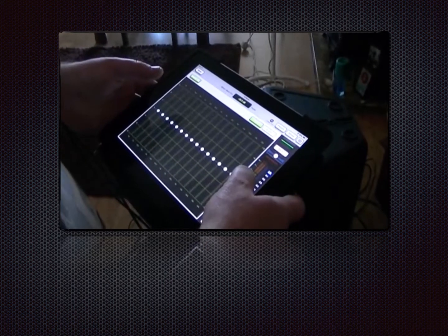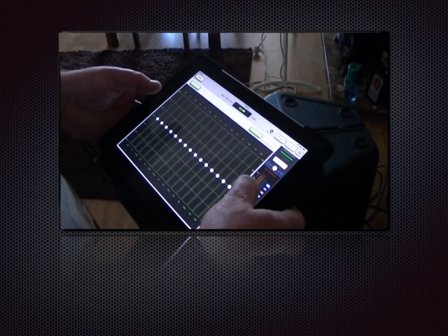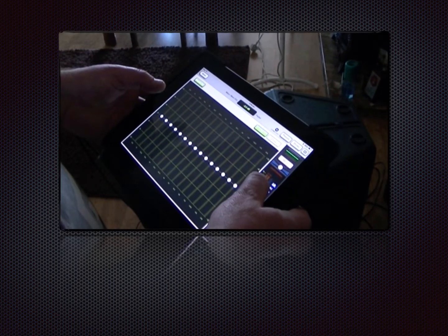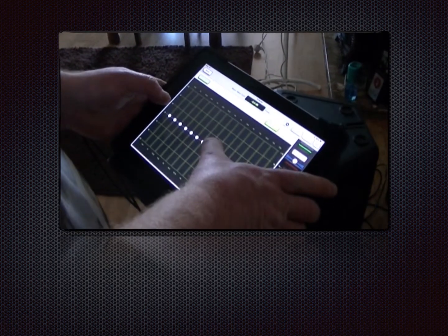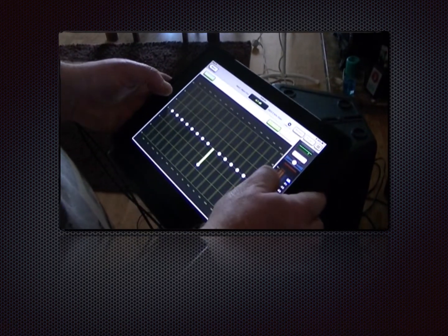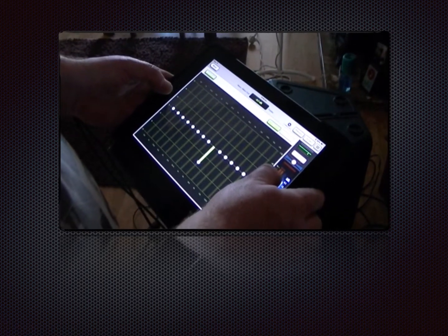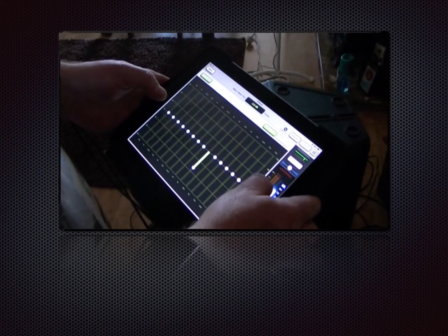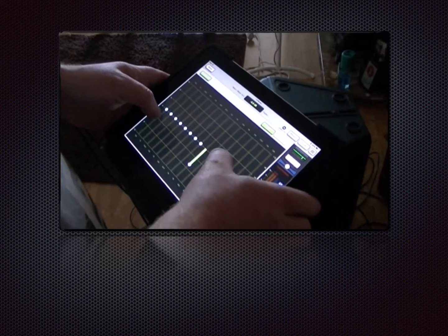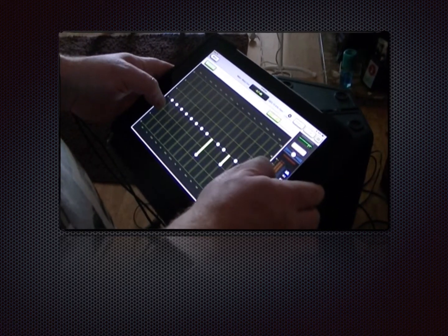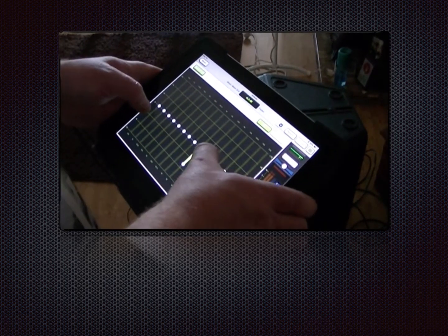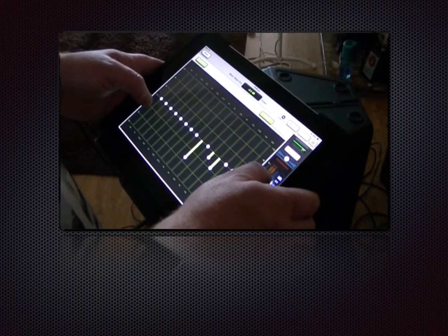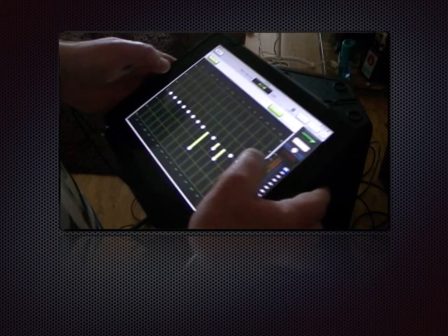Now we need to raise the volume of the lead vocal microphone, inducing feedback. Once we start to hear feedback, we use the graphic equalizer to cut the gain on the frequency band where the frequency occurs. We repeat this process until either there's no more feedback or until we hear numerous frequencies at once, in which case we have reached the maximum headroom achievable by the system. We then lower the microphone volume to an appropriate level.